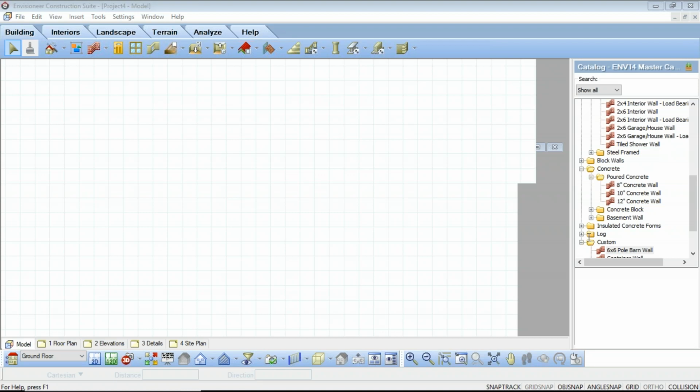One question is, does a larger site require more memory than a smaller site? I believe you're referring to the terrain size. That question is a little tricky. If it's just going to be a 300-foot by 300-foot square, then no, it won't be that much more memory needed. However, if you are adding in spot points and your site is bigger, then yes, it will take up a little bit more memory because it's got to go through and analyze that model and all of the contours. If it's just a flat site, then no, it's not going to be that much of a difference.